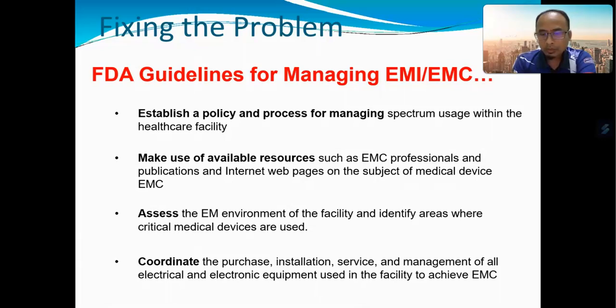So in order to achieve that kind of goal, what we need to do is choose appropriate devices to test the EMC standard for the medical device, such as IEC 60601.